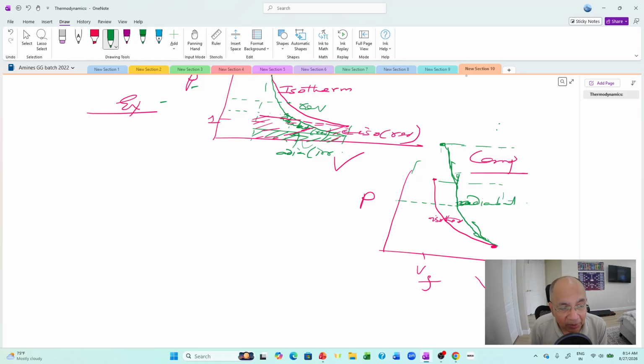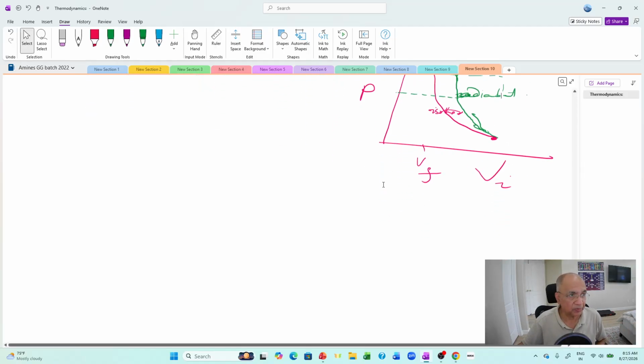So if it is irreversible compression, both in adiabatic and isothermal, adiabatic will have greater irreversible work than isothermal. In the reversible process, obviously adiabatic is more than isothermal, and also in the irreversible process, adiabatic is more than isothermal, which we have already discussed before and now. But for the first time, we are comparing adiabatic and isothermal graphs in reversible and also irreversible.